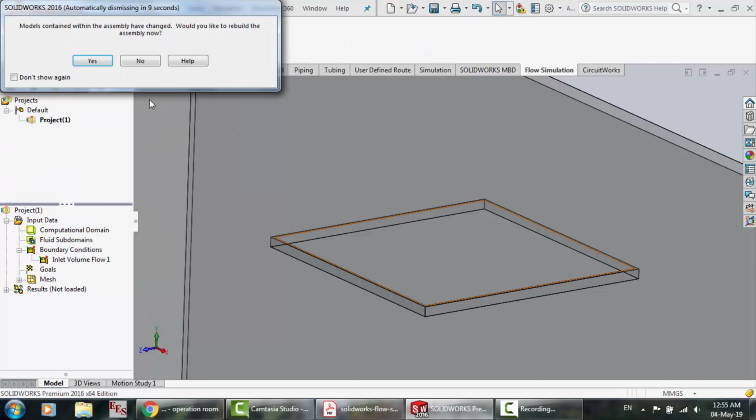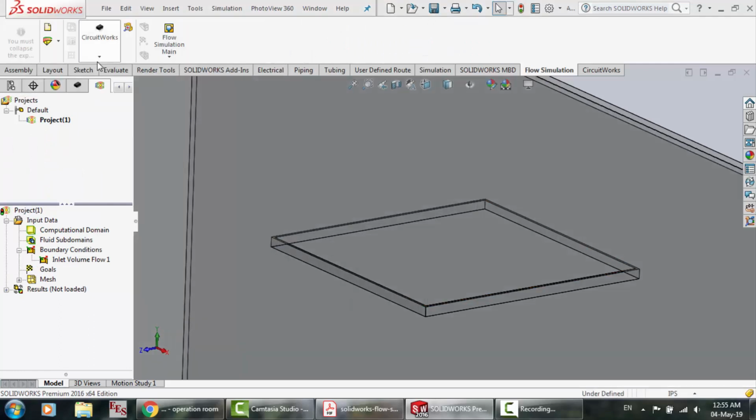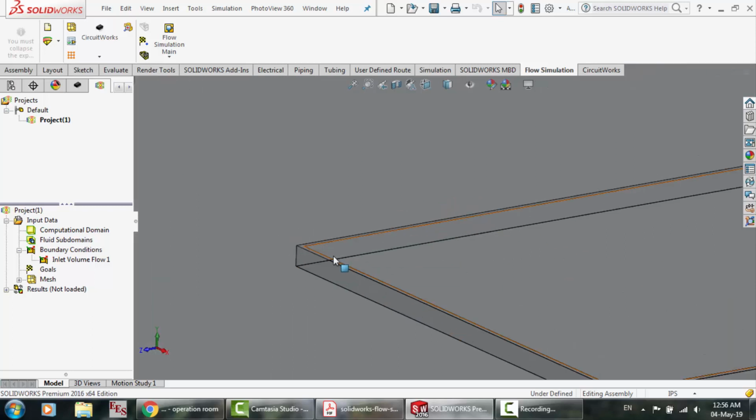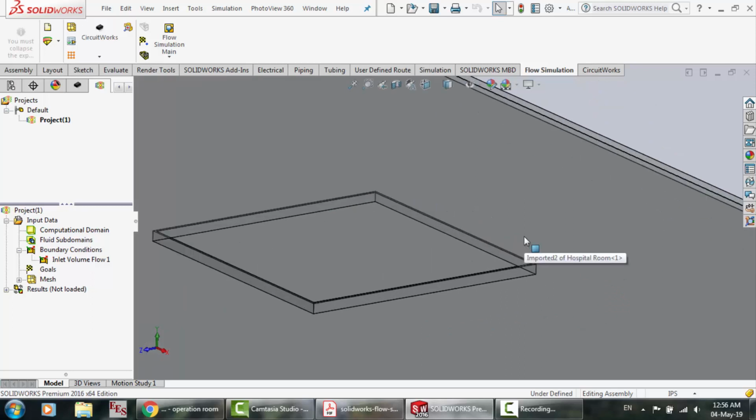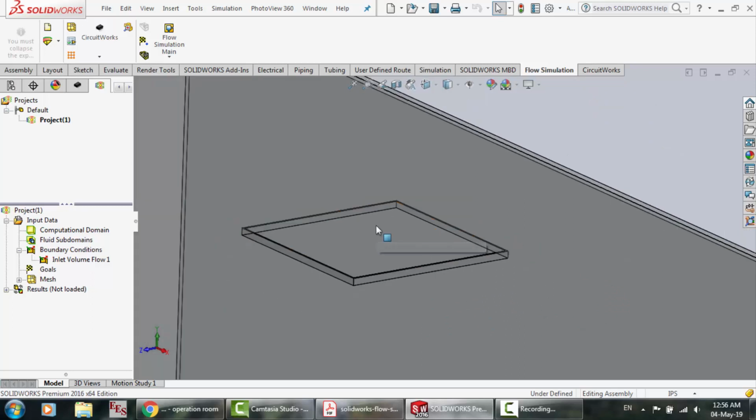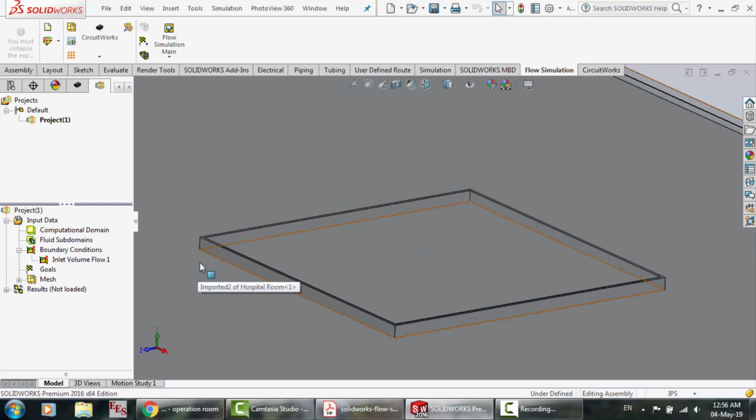So yes, I wanna see the update. It will tell me that this may change the dimensions of the inlet or outlet area, and this of course will affect the velocity. So I'm telling you, consider it from the beginning. You make it greater, and then you select the extrude or the dimensions while you carry out the extrusion. Use the real dimensions of the area you want. Okay, so you can do this without any problem.